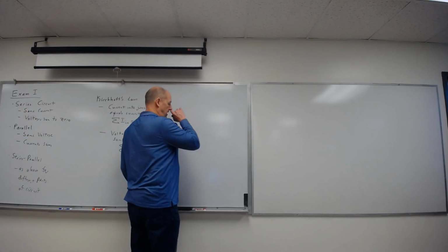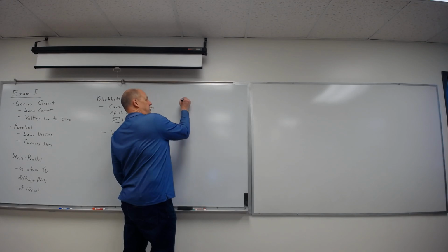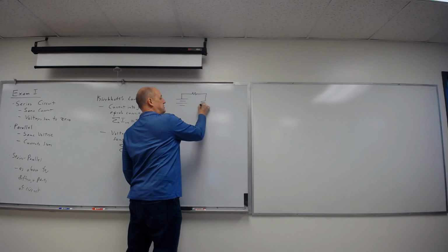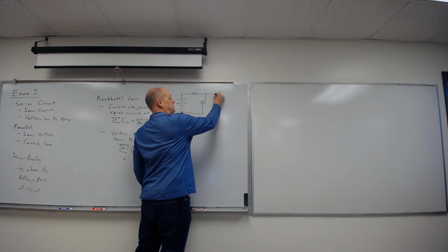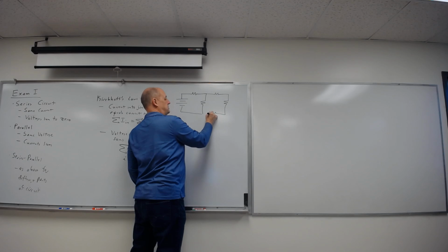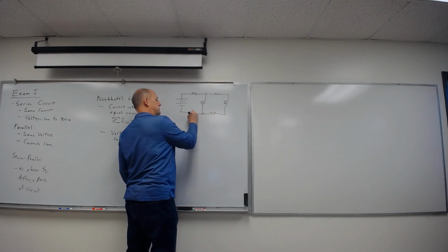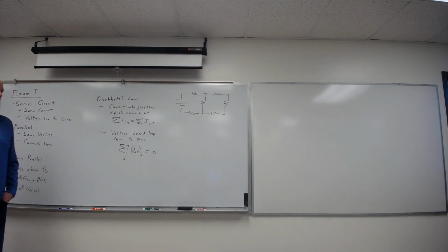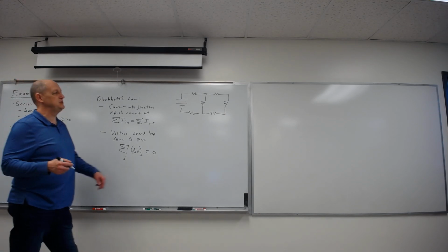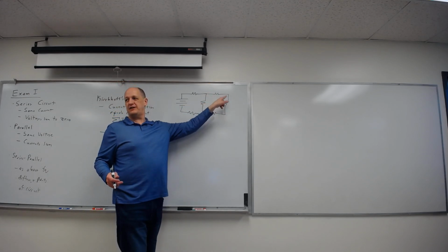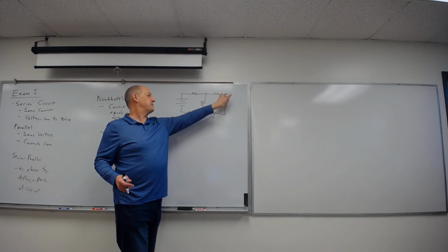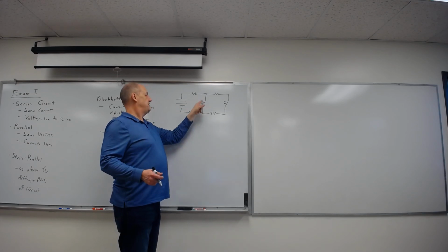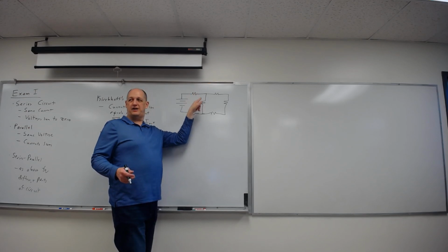So I'll just write a couple down. I'm not going to solve them all unless you want me to. But if I have a circuit like that, here, I'll just put a resistor here. I can solve that one pretty easily by 2 methods, actually. Number 1, I can go in and do these 3 resistors are in series, right? Replace them with a single one. Yeah. That resistor's in parallel with this. Combine them, replace it with a single resistor. That resistor then will be in series with these 2, and I end up with just a series circuit.